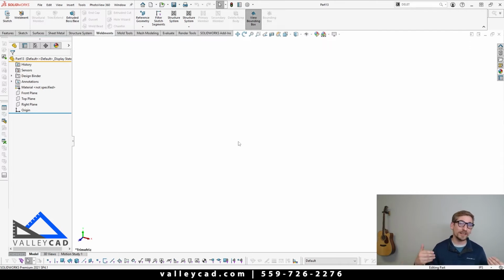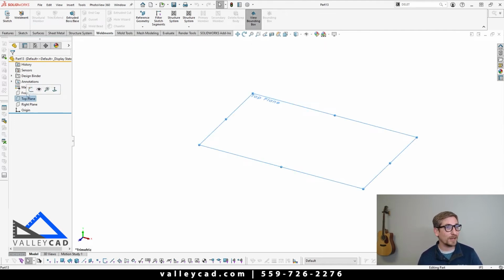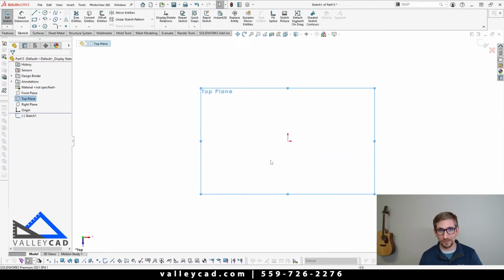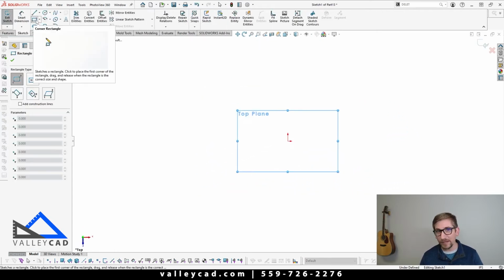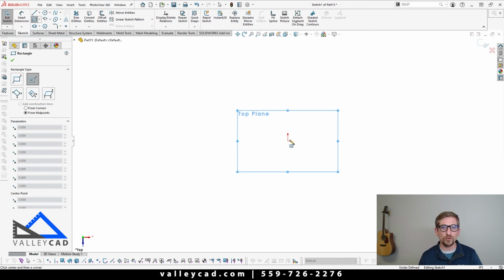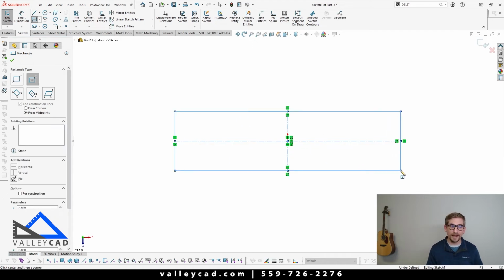And it's actually going to set up for a 3D sketch for us, right? 3D sketching, normally people go into a cold sweat going, oh no, not 3D sketching. But it's actually going to be quite a bit easier than that. So coming in here, we're going to come onto my top plane and we'll simply create a new simple boss base extrusion from this. So simply activating a rectangle command. We'll do center corner rectangle because like I said, it's a great practice to try to keep your origin centered about your part for the sake of mirroring and other patterning approaches.